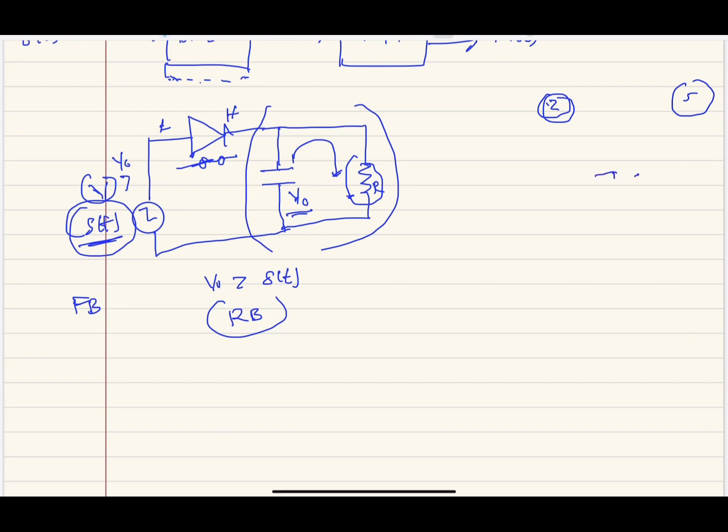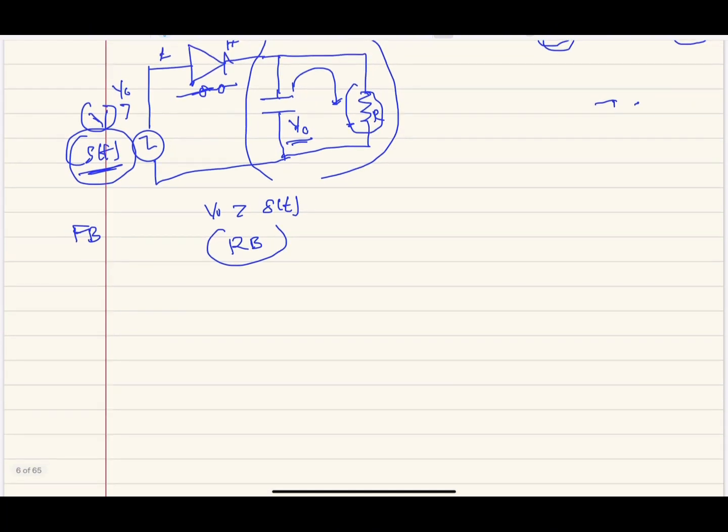In this case, we will get the capacitor voltage waveform to be the same as that of the envelope of the AM wave that we are trying to demodulate, and therefore the envelope will be almost similar to the modulating signal, which is the message signal that we are looking for. But not to waste much time, we will try to do some mathematical analysis for the switching modulator or the envelope detector.